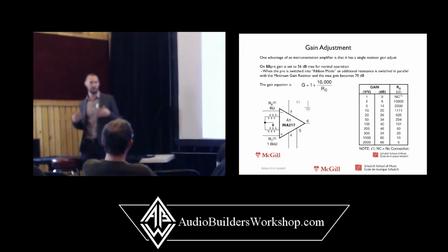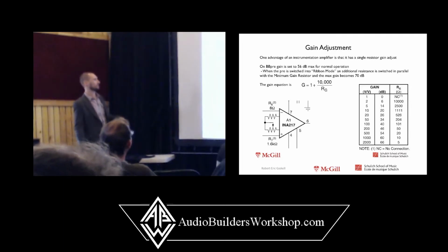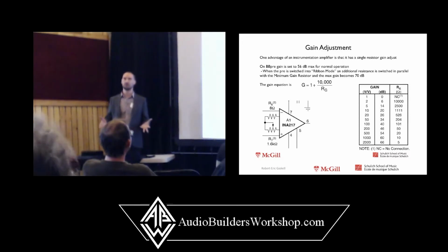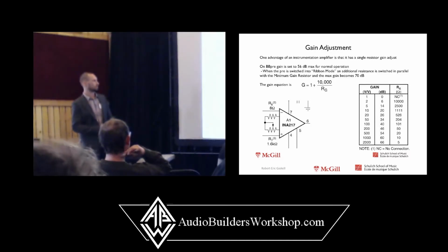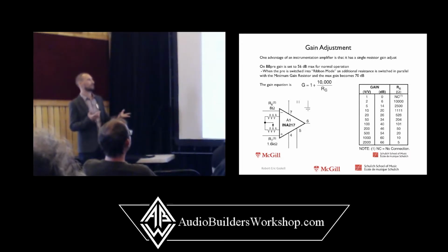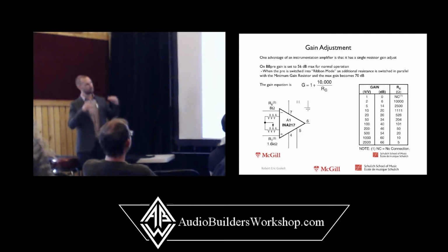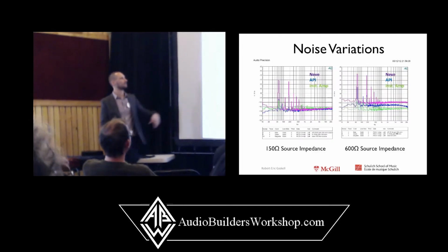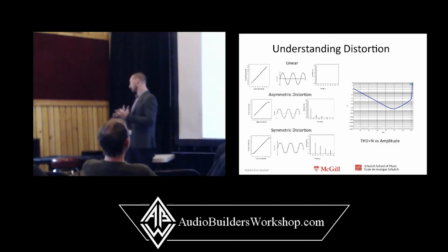So if we look at equivalent input noises of microphone preamplifiers, often they have better relative performance at high gain than they do at low gain because of the contribution of the thermal noise of the resistors. I think that's interesting. It becomes a challenge to create a microphone preamplifier that has low noise at relatively low gain. But that's just one of the small, subtle problems that can be an interesting thing to try to improve upon as electronics get better and better.